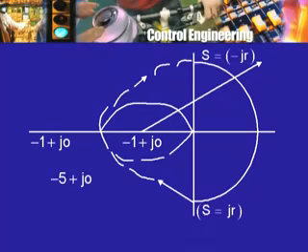So, this is a conclusion that we can draw if the image of the Nyquist contour goes through this point minus 1 plus j 0. The conclusion is that there is an intersection, in the root locus language, of the root locus with the j omega axis, or in terms of characteristic polynomial roots, there will be roots of the characteristic polynomial on the j omega axis.